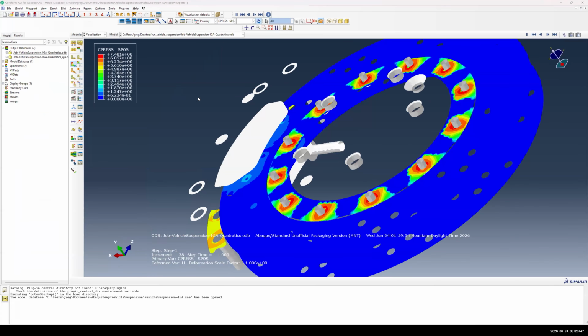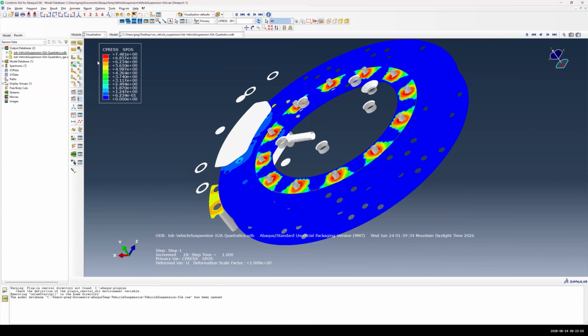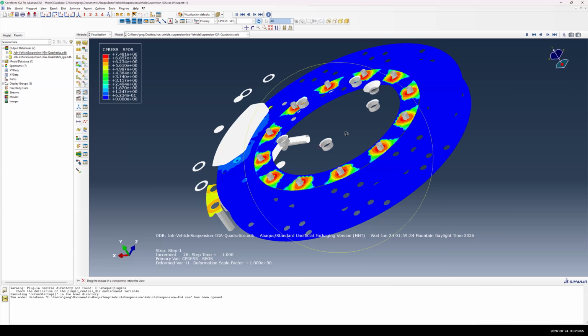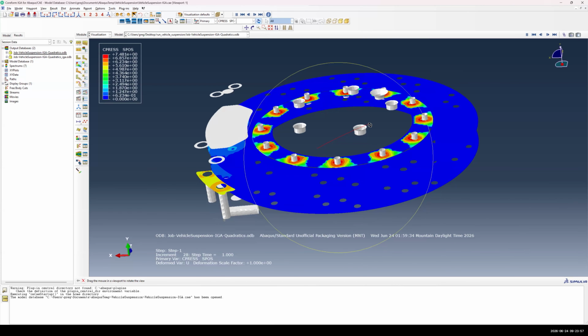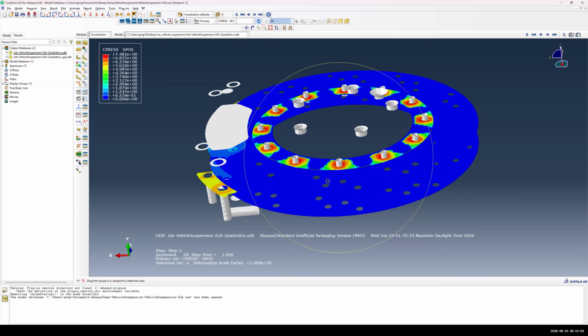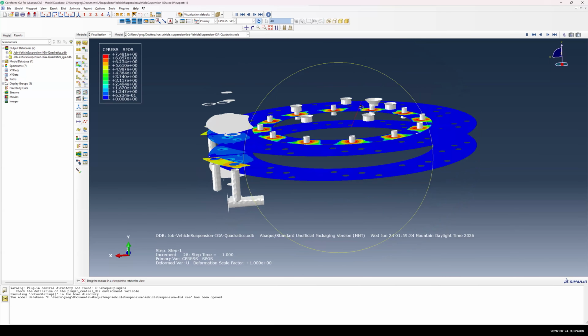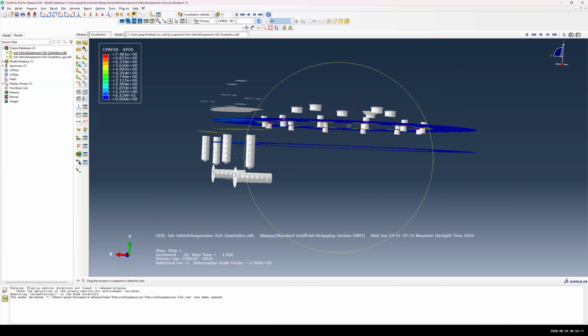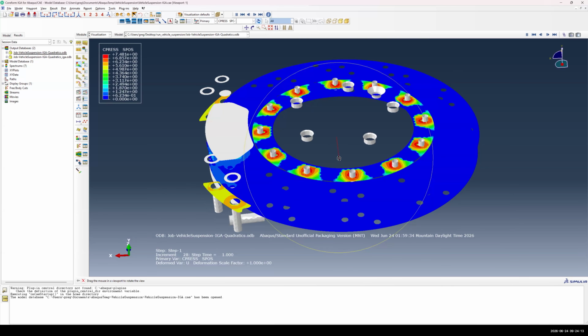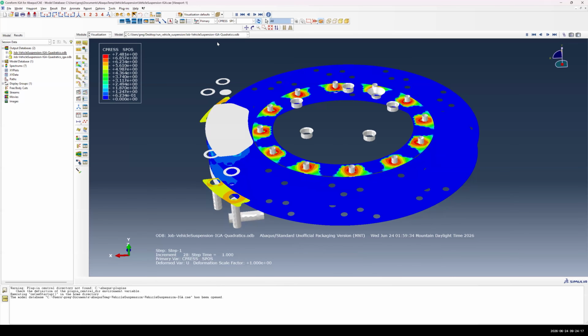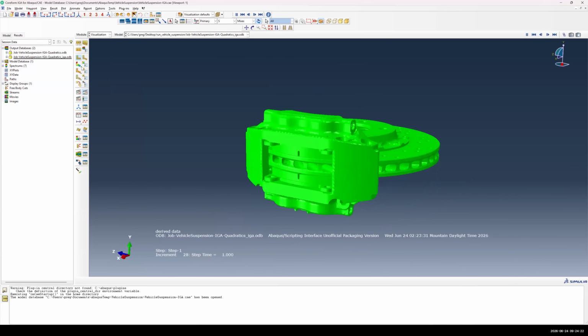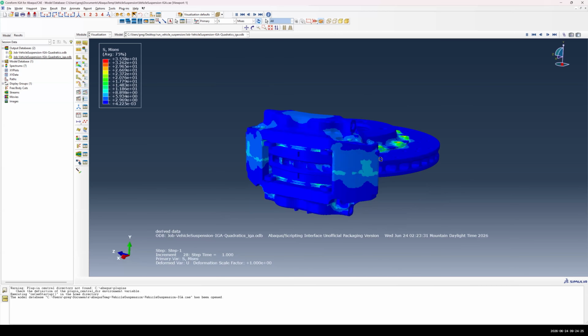So I wanted to show, one of the things that we create as part of the simulations is surfaces of our boundary conditions as well as our contact surfaces. And you can actually view those in the standard output database that Abaqus exports. And so here I can look at contact pressures for my simulation. Here on the final time step, I can see that there is contact going on in my simulation, as well as I can look at the full field results like our stresses.